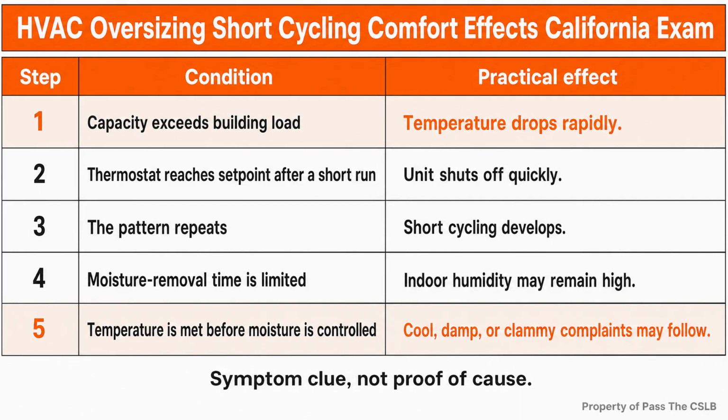The CF1R is the certificate of compliance. In the source material, it belongs to the design and permit phase. It identifies the energy features, calculation methods, and performance specifications for the project. The enforcement agency requires the building design plans and energy specifications to be submitted with the permit application. The CF1R must be signed by a responsible person who is eligible under the Business and Professions Code.